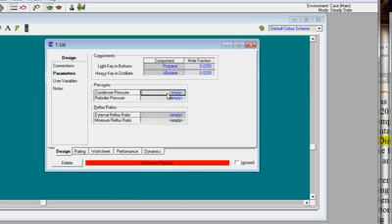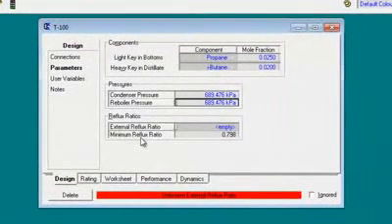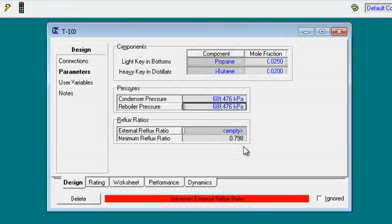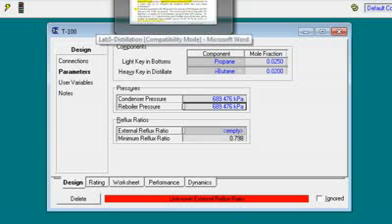Now for the pressure, we enter the same pressure as the feed, which is 100 psi gauge. As we can see here, the warning is unknown pressure, and the same way for here also. This one is also 100 psi gauge. And if you are asked about the minimum reflux ratio, it is 0.798, and the external reflux ratio should always be equal to or more than this ratio. So now it's done, and let's go to the worksheet.